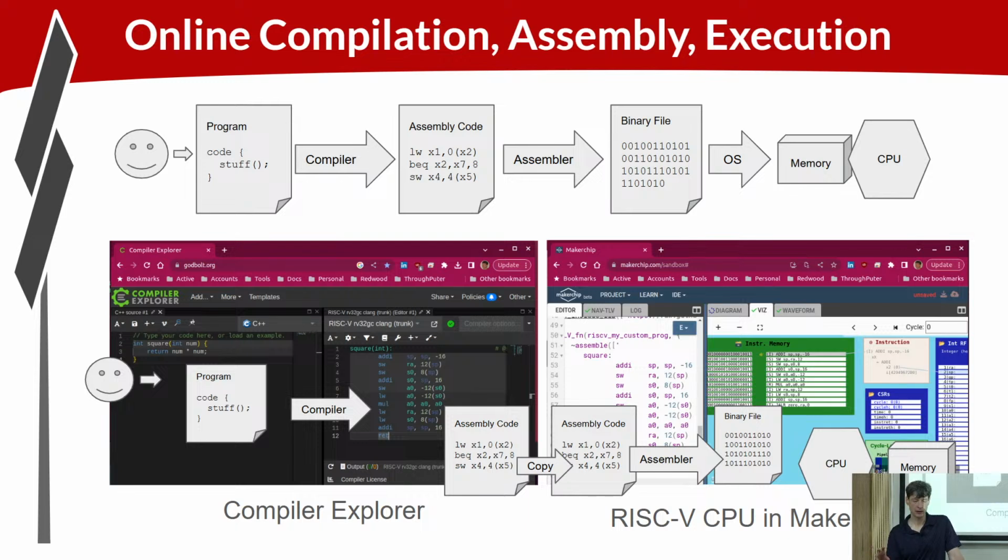The Warp-V CPU generator using TL-Verilog has a built-in assembler. It uses the macro preprocessor that we layer on top of TL-Verilog. So you can drop your assembly code straight into there. When you compile your code, the macro preprocessing assembles your code, turns it into bits, creates an instruction memory that's hard-coded with those bits, and you execute your code out of there.